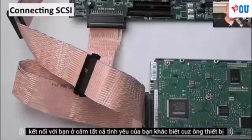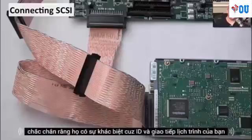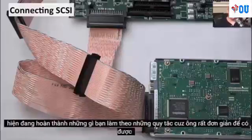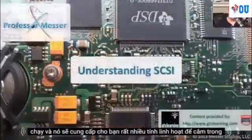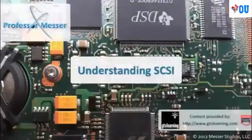So you simply plug into the closest connector to you and plug in all of your different SCSI devices, make sure they have different SCSI IDs, and your SCSI communication is now complete. Once you follow those rules, SCSI is very simple to get running, and it's going to provide you with a lot of flexibility to plug in multiple storage devices.